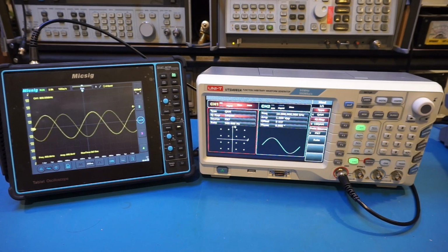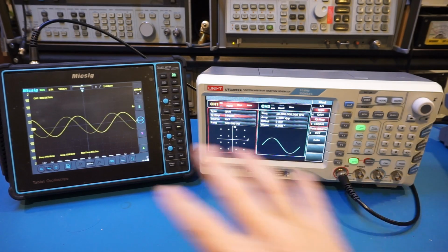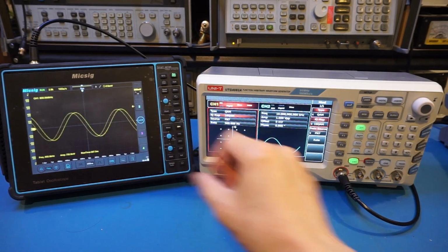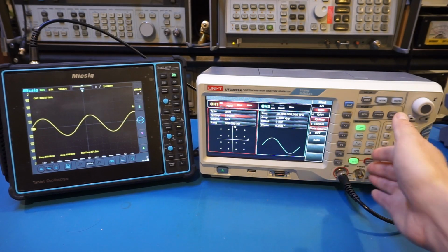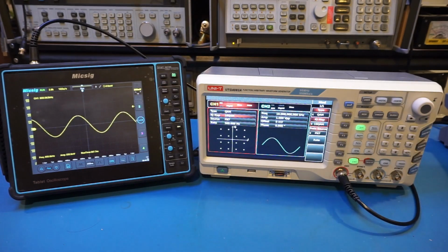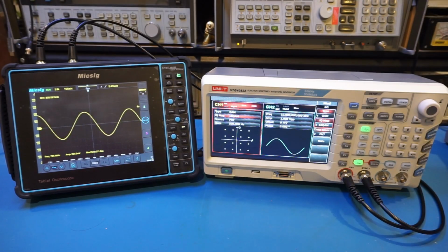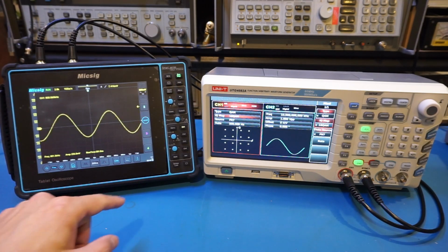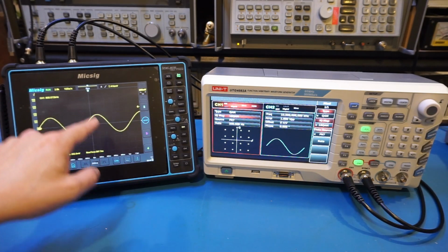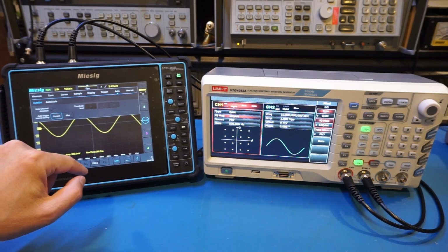Now, to produce an eye diagram, you will need to trigger on the frame instead of the rising edge of the actual signal. This is where the external trigger comes in. So we will have to use a sync signal putting into channel 2. Let me set that up. Alright, so now I have put the sync output connected to channel 2. So let's actually change the trigger source to see if I can figure this out. Trigger.